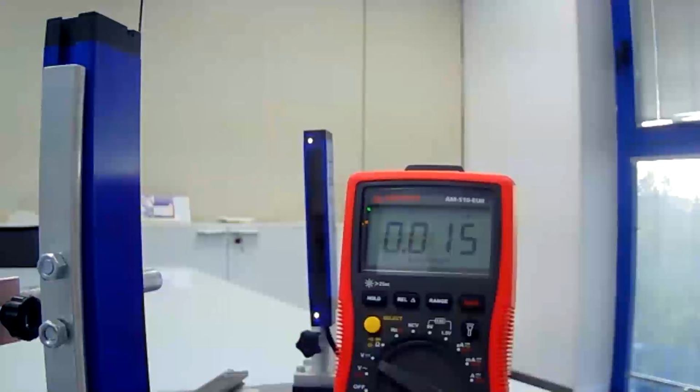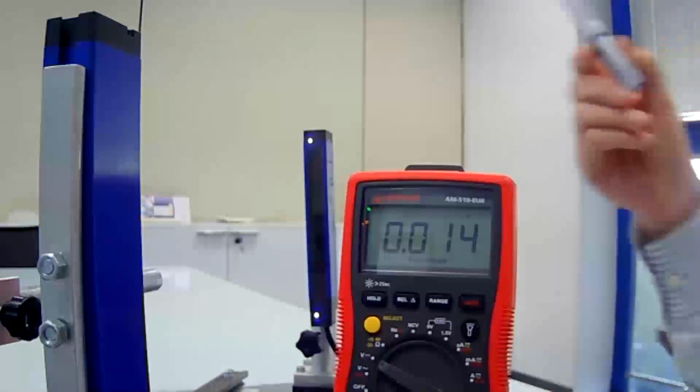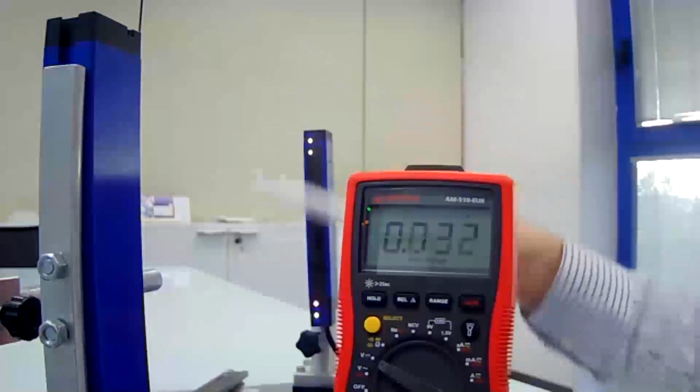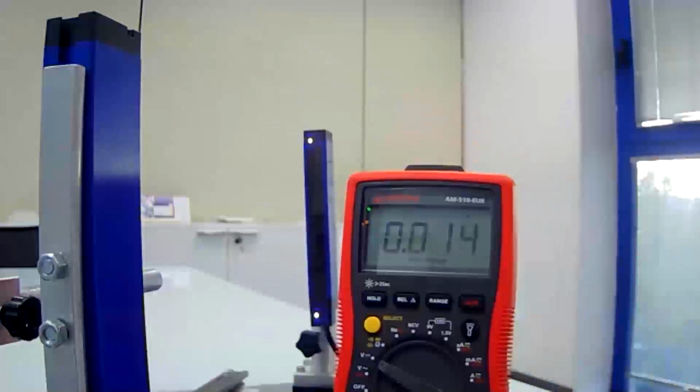So the solution is to connect the blanking wire to the ground and restart the sensor, and the sensor now cancels the blanking function that we set with the previous connection. After a while, the sensor is working, and now we don't have any blanking LED, so we can restart to work in a simple way.